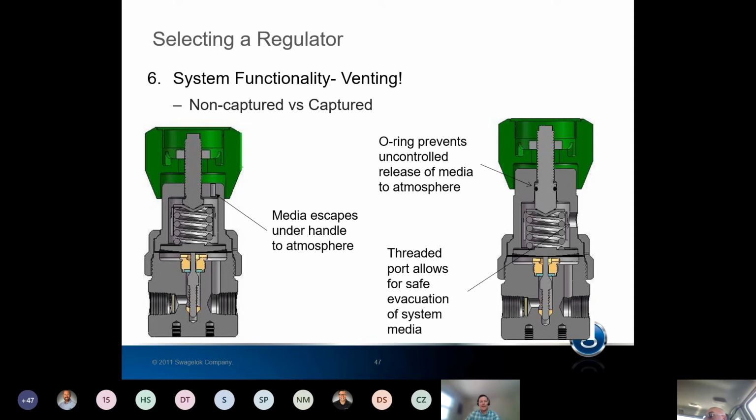Should gas escape through the sensing mechanism, it can be directed to a vent line or a flare header. It can even be pushed out the roof of a shed, but just pipe it away safely. Again, those are two separate choices you can make: self-venting or captured vent.